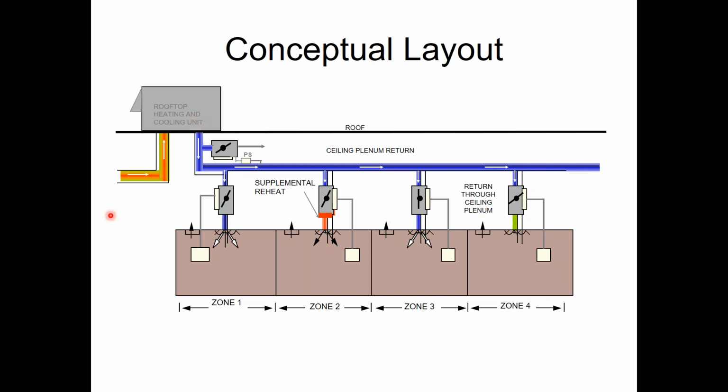What you're thinking, Hardik, is more of a VAV style system where I have direct control of the discharge air. Now, with that being said, we are going to put a discharge air temperature sensor in this duct system, but we're going to use it as a limit protection, which I'll explain in a little bit. All right, let's keep on moving here.